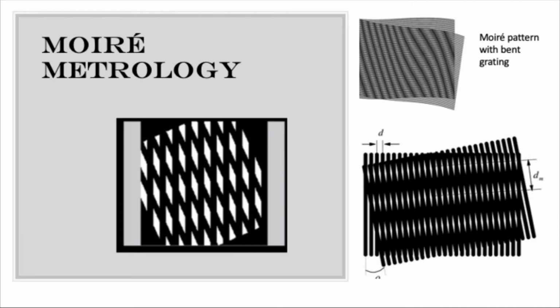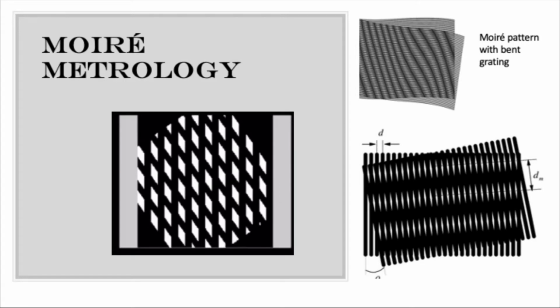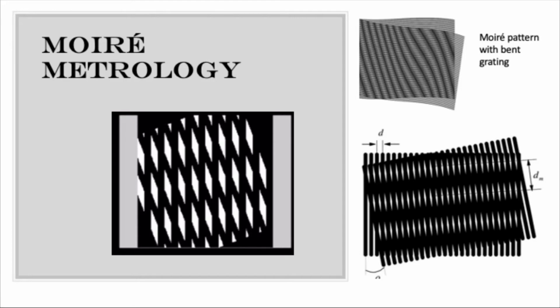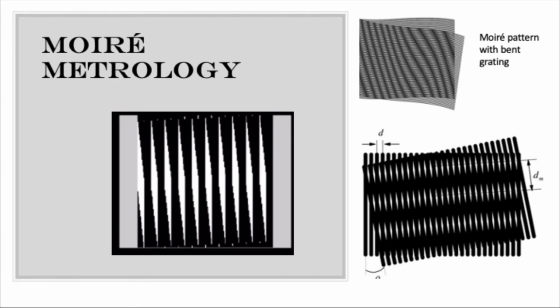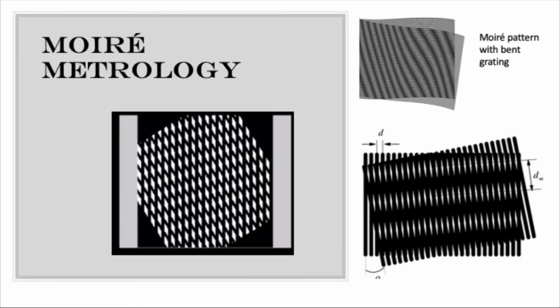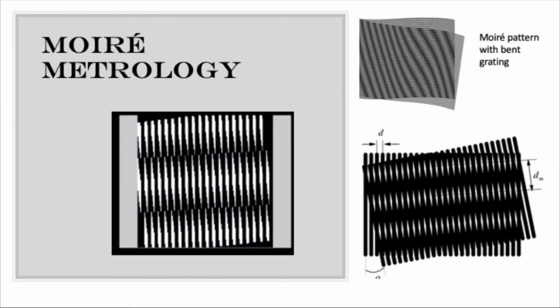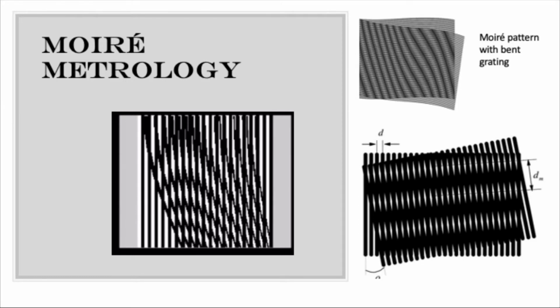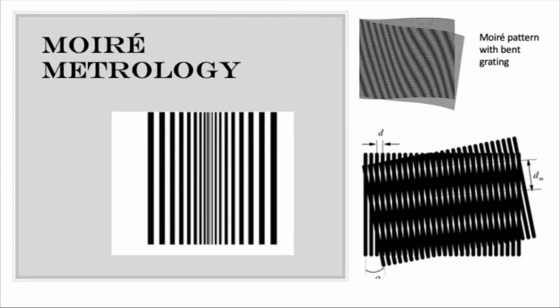It's a really cool technique in which you can overlap two geometric patterns, in our case straight line gratings, and the superposition creates a net fringe pattern as a result of overlapping those two geometric patterns. What's really cool about it though is that a small change in one of the gratings will have a large amplified effect in the overall fringe pattern. So we decided to use this to measure nanometer scale distortion because small changes in the first grating pattern when imaged onto the second would cause an overall shift in the moiré pattern, and from that we could infer distortion.